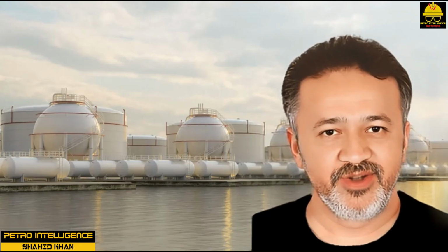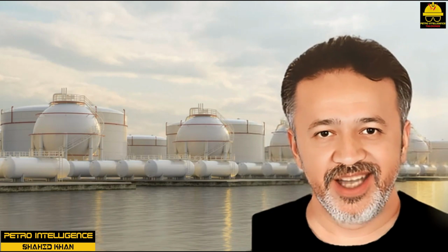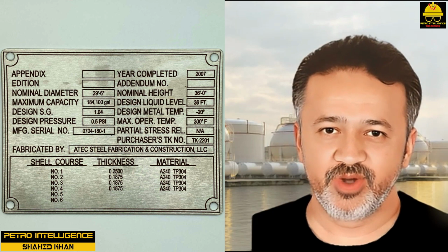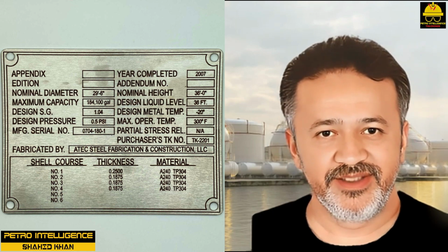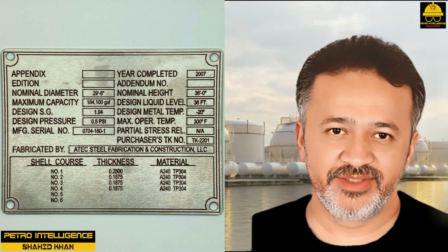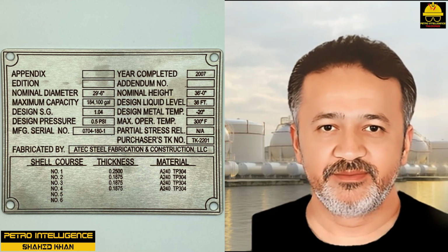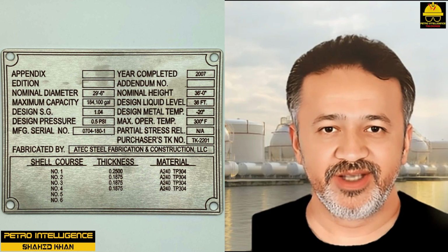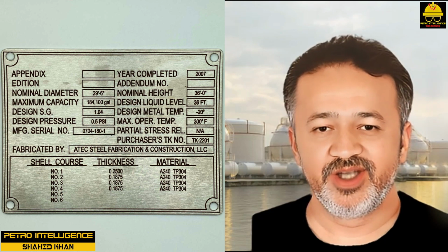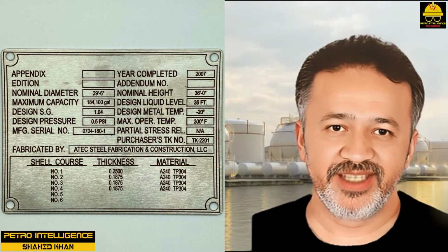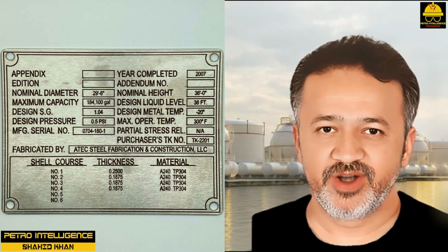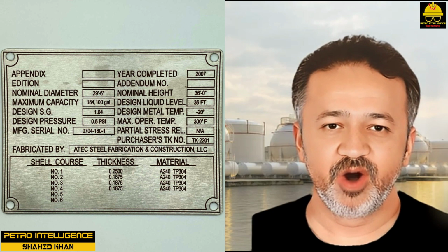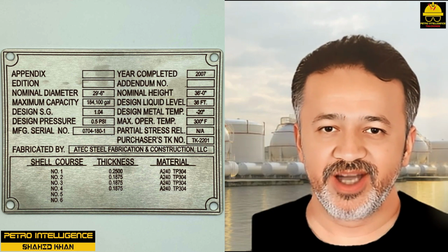Vessel documentation and design. Each vessel will include a code stamp that will indicate high pressure and high temperature ratings, manufacturer, date, type of metal, storage capacity, and special precautions. Most vessel documentation includes strapping tables that will allow a technician access to data that can be used to identify capacity. For above-ground storage, the ASME, American Society of Mechanical Engineers, Code, Section 8 governs vessels that have pressures greater than 15 psig.